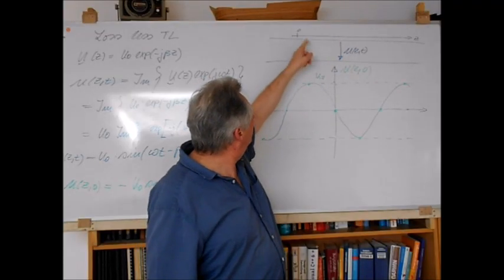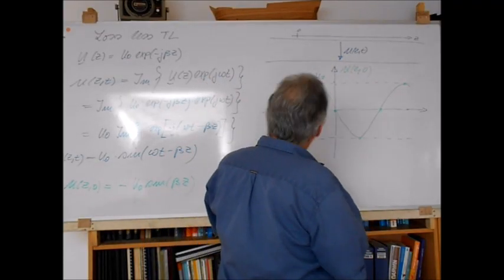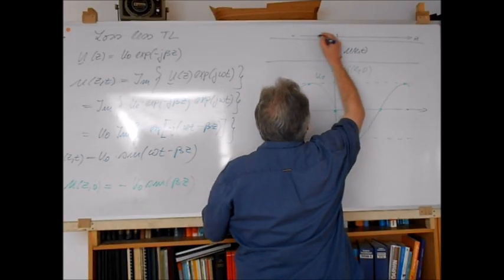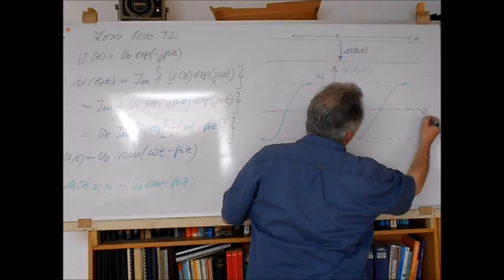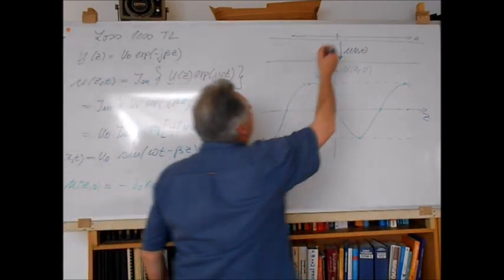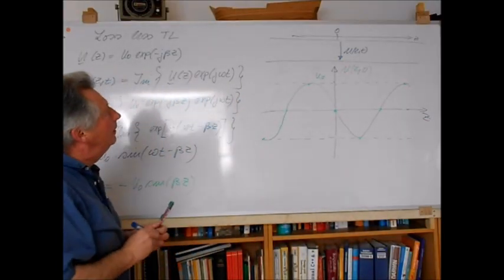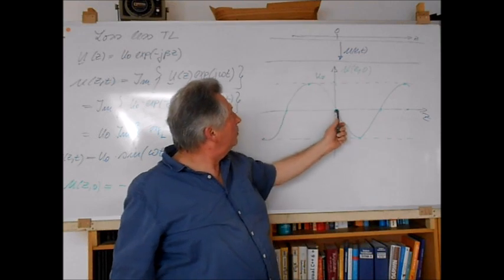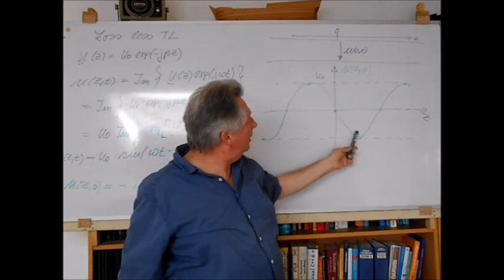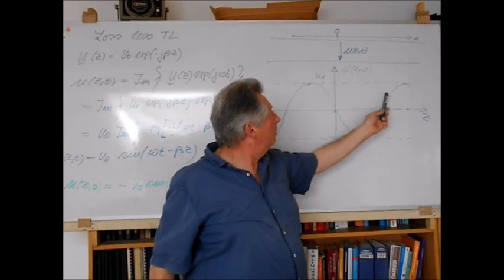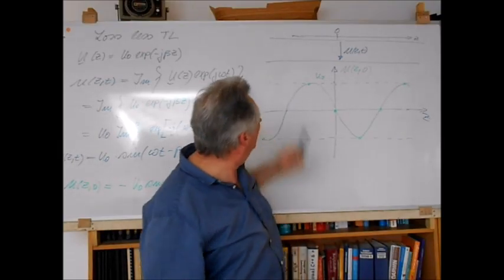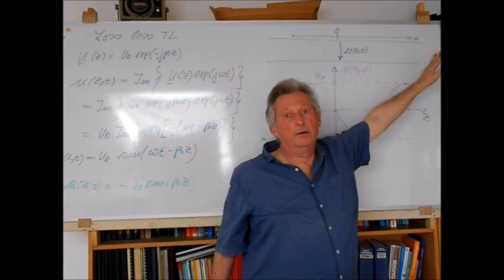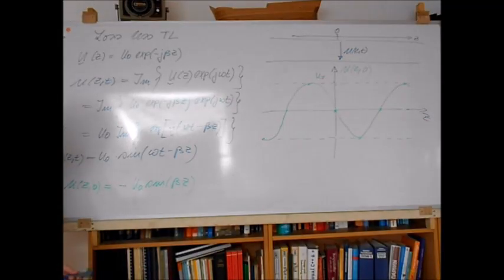then, for example, at this, oh, I should perhaps sketch this zero here. It's more appropriate. Here we have a zero, and then here we have the same z coordinate. This is a zero here. That means if we have z equal to 0, then also the voltage will be 0. Here we would have a negative voltage across the transmission line. Here we would have a positive voltage, and so on. So along the transmission line, you in principle will have a sinusoidal voltage distribution.